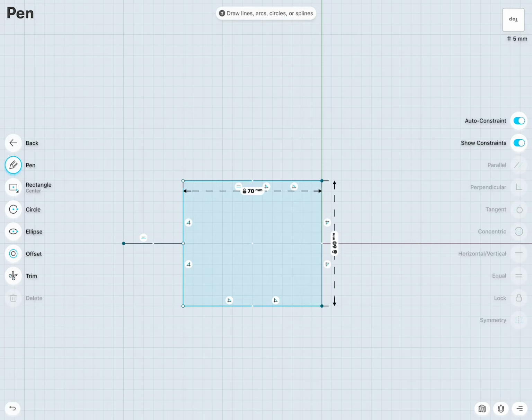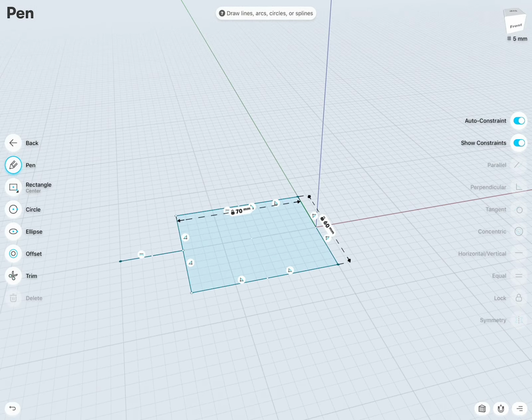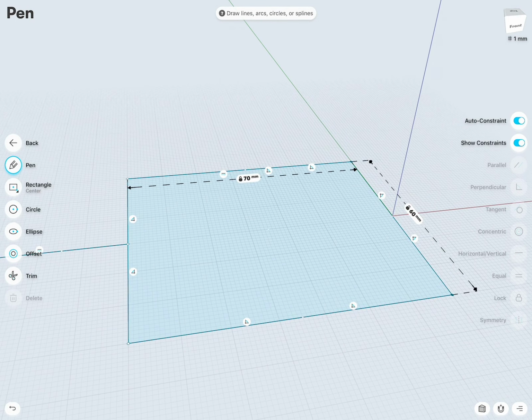So the spatula has a rounded corner. I could put this into the sketch, but that makes the sketch way too complicated. A very good approach when you start to learn how to create all these sketches and the geometry, try to really create the bare minimum of elements for the sketch. That makes sketches easier to manipulate, because the rounding we can do via geometry tools.